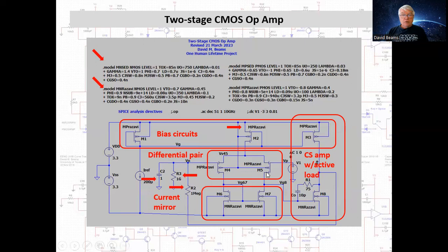Now, if you want to do an analysis involving this op amp with a real application circuit, you can remove C2, or you could set it to 1 femtofarad, 1,000th of a picofarad, essentially 0, and then you can change the values of resistors R2 and R3 to the realistic values that would be applicable to your application, and you can run your analyses.